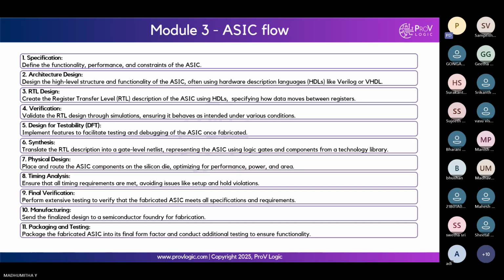If 1 gigahertz is the frequency, what is the time period? 1 nanosecond. So what does that mean? The data which our flip-flops are going to carry and propagate must not take more than 1 nanosecond. That is again called a constraint, a timing constraint. We can call it like that. So like this, many constraints will be given by the client. We have to make sure that our layout, which we are going to develop at the end of the physical design, must adhere to all of these constraints. We will look into all of this in detail in the course.